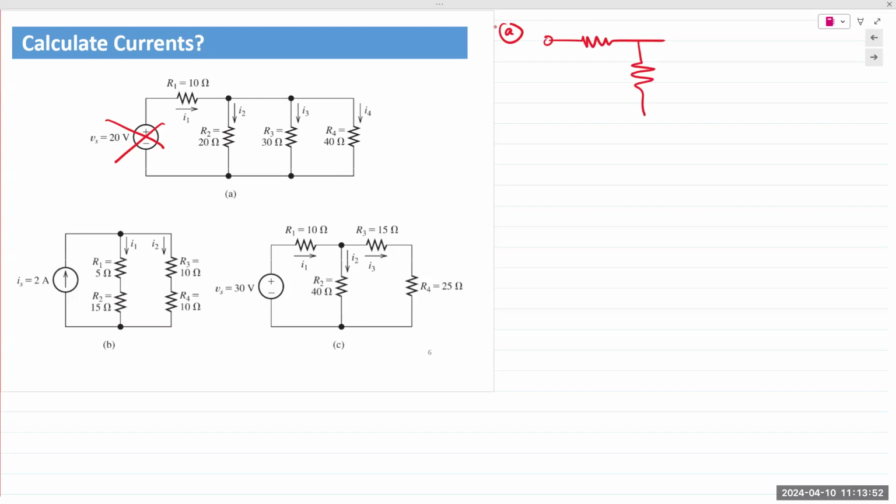So in this case, what do we see? We start at the farthest end, and we move towards the measurement terminal. In this case, we start at the rightmost end, and you move forward towards the front end. What do we see? R4 is connected. R4 has 2 terminals. Those 2 terminals are connected to R3, and they're connected to R2. So they are in parallel. So the next step after this, R3 and R4.